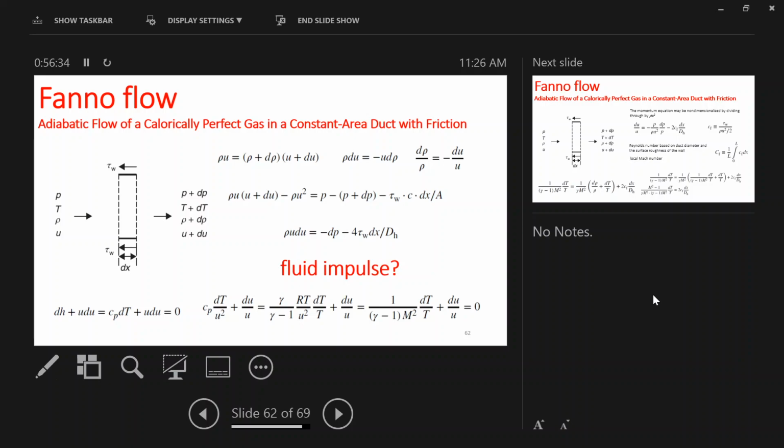Because friction is a function of fluid properties and flow properties as well, right? As well as the wall condition. Remember the boundary layers and everything. So yeah, the wall friction changes. What is the main equation we have for the wall friction? Negative mu du over dy, right?